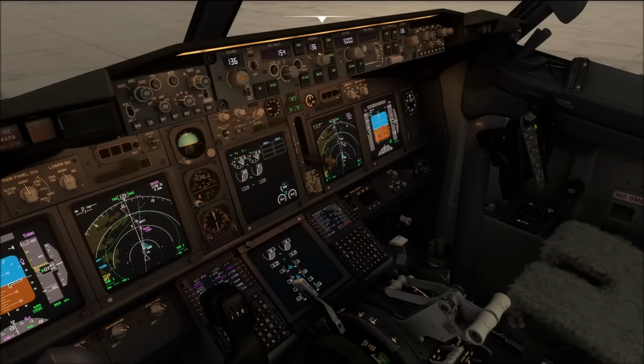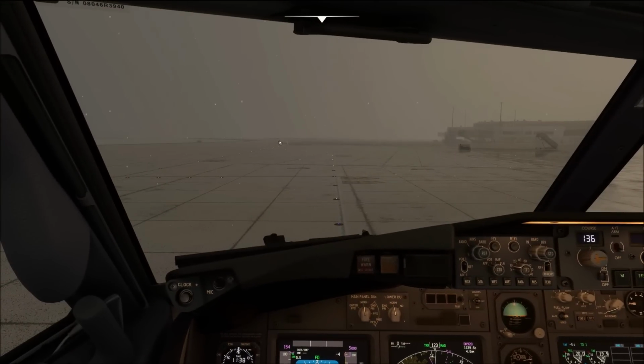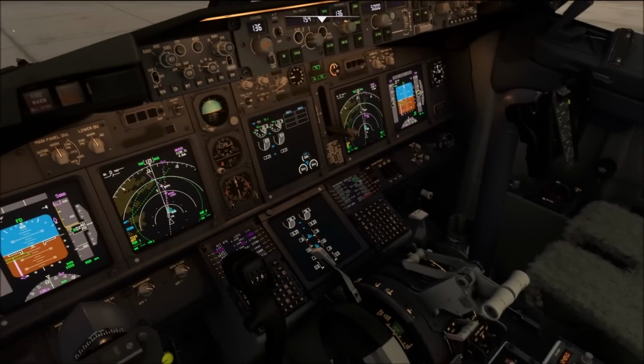Once the flaps are extended to 40, you're going to retract them again, in case you have to taxi above contaminated surfaces. So that means if you're taxiing, for example, with freezing conditions right now, or if there is snow on the ground, as there definitely is, as we can see outside the airplane right now.